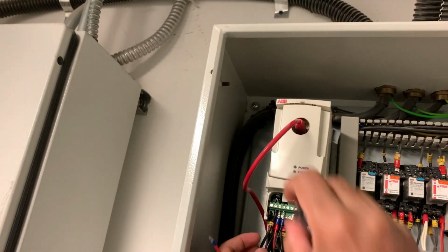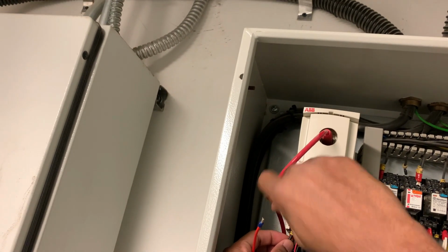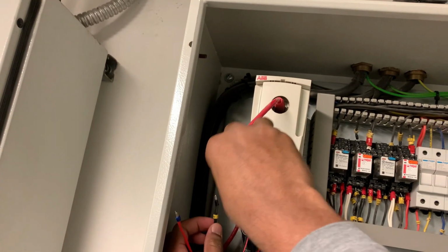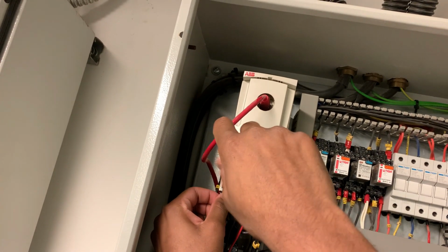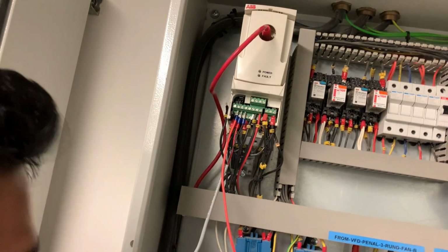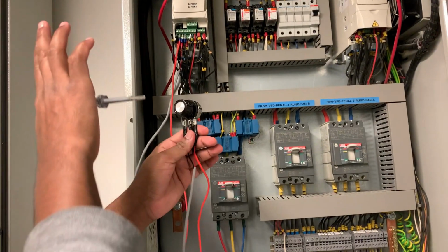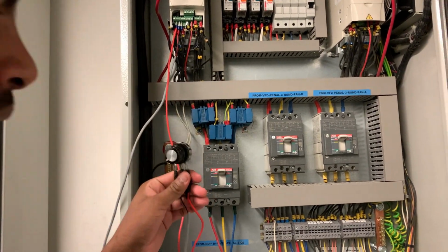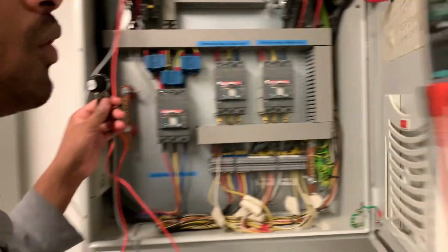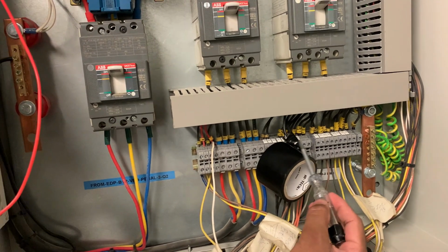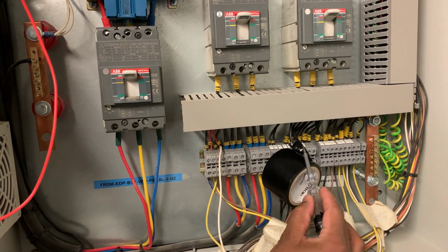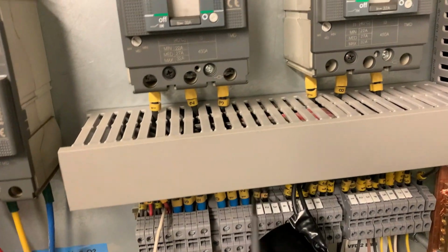So what I'm doing, I'm removing this first number and I'm connecting our potentiometer output to this. I have connected the output of the potentiometer in the VFD, but the VFD will not run now. Why? Because there is no 24 volt output. I have shorted these two cables for now because there is no fire signal, so it will not run. That's why we shorted the 2-4 cable so that the other 4 have 24 volts.